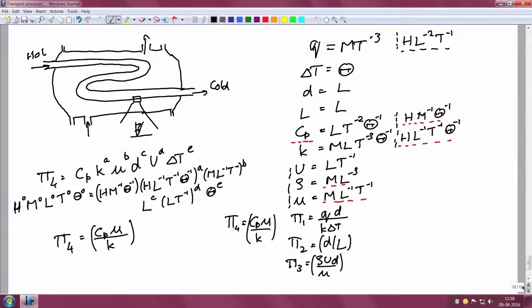We had looked at the case of a particle settling in a fluid, in which case the drag force non-dimensionalized by the viscosity, velocity and diameter depends only upon one non-dimensional number, the Reynolds number, in addition to the aspect ratio, for example, the ratio of the diameter of the particle to the size of the system. And most recently we were looking at the heat transfer in a heat exchanger, where we had identified the dimensional groups. The number of dimensional groups is quite large. It is 9 in this case.